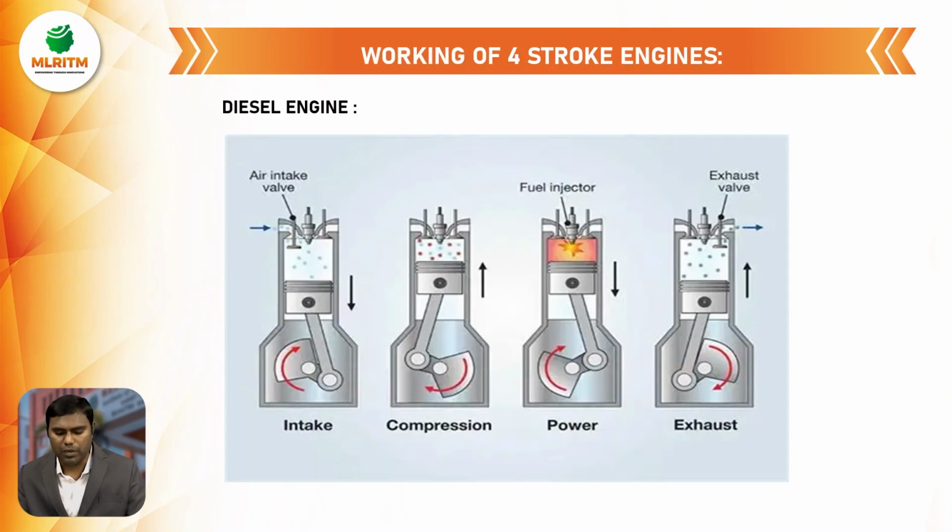Then coming to the working of a 4-stroke diesel engine. Actually, 4 strokes means we have a suction stroke, compression stroke, expansion or power stroke, and exhaust stroke. A suction stroke is also called an intake stroke. In a suction stroke, the inlet valve is open and the exhaust valve is closed. If it is a diesel engine, only air enters the engine cylinder through the inlet valve.